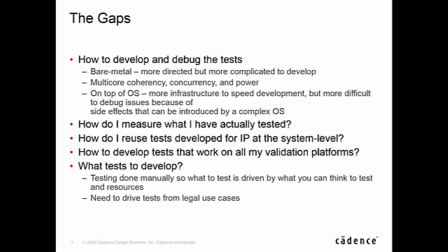a pure functional view of saying, okay, I can't write all these tests, so I'm just going to run my operating system and run some application tests on top of my operating system and prove out that my SoC is going to operate under the working conditions that it's going to see in actual application, which is a reasonable approach to at least getting to the point of the use cases that are going to be seen by the SoC.